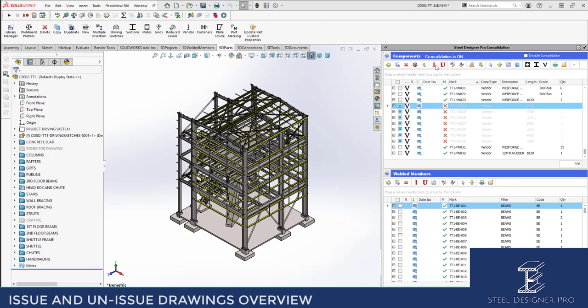Each time you make a revision change and you update your drawing, a history of that file can then be looked at, and you can view what that file went through, including changing marks, which is a really good tool. The next one, obviously, is if you've issued something and you didn't actually give it to somebody, you need to unissue it. You can then select to unissue that item.